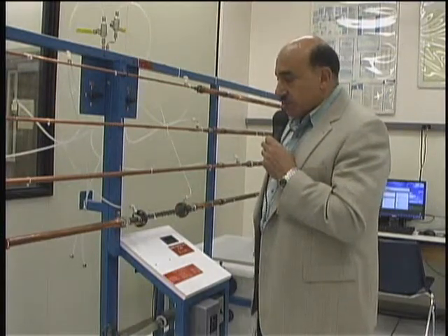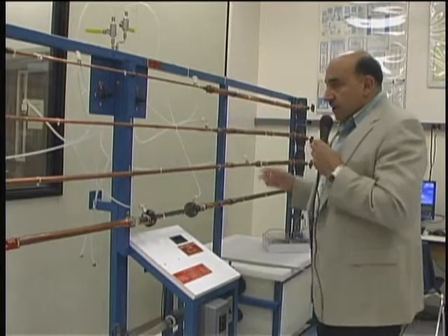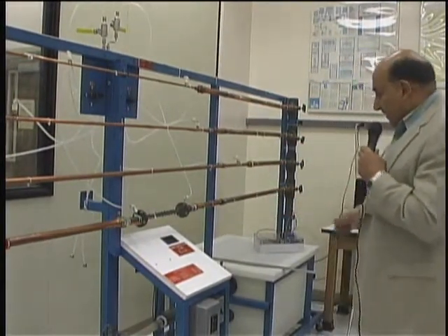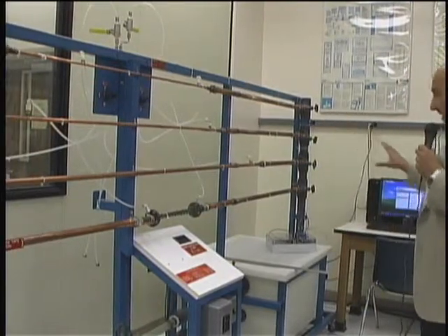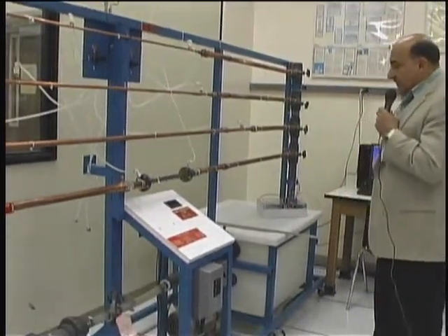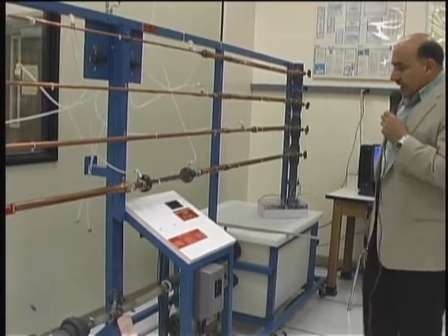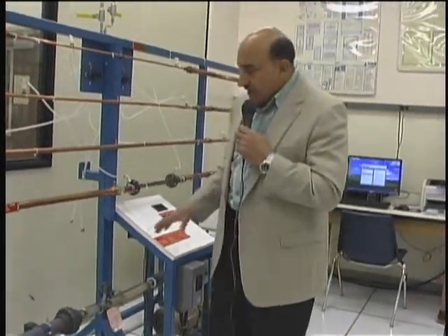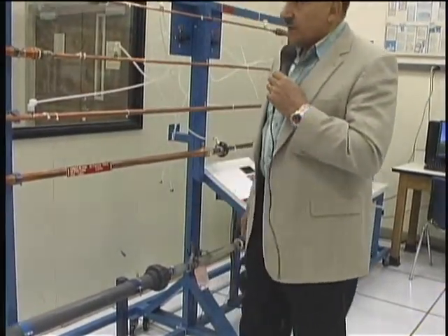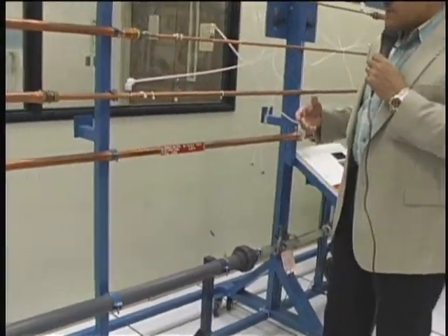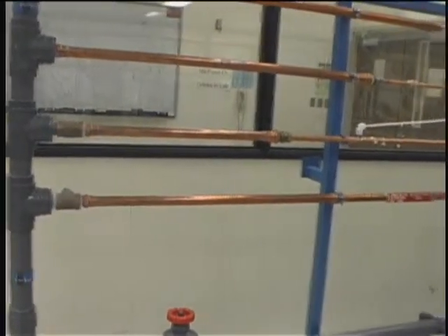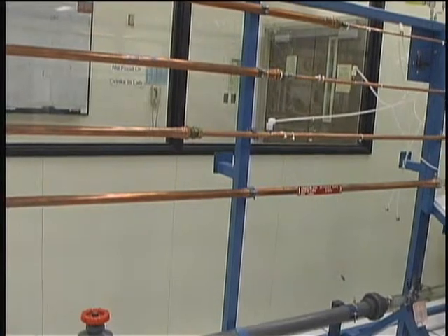and do our measurements as well. So this is all in parallel, and the flow is a closed circuit. So generally the flow here, we have a fluid flow, we have a return tank, it's a water driven system, and you've got a main pipe for the flow, and then it distributes the flow in parallel. In our measurements, we're going to shut off all of the valves except for one where we do the measurements.